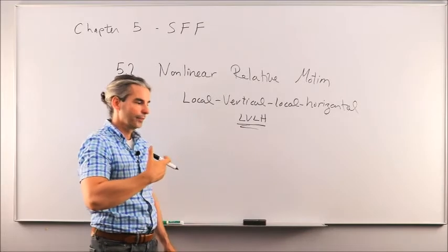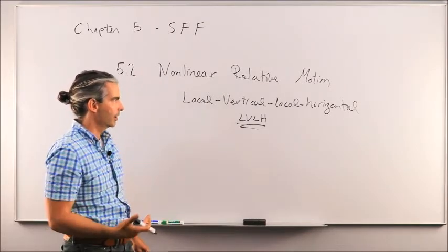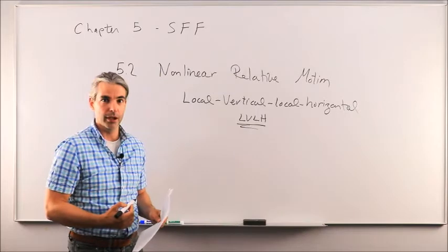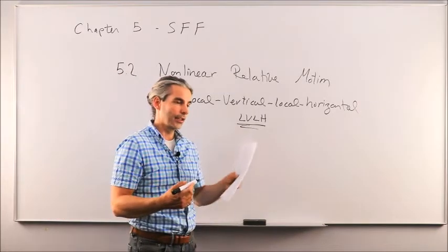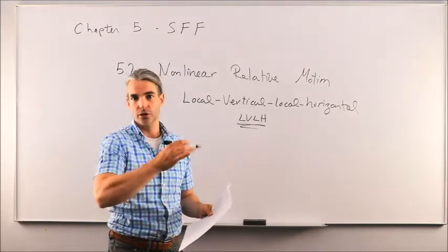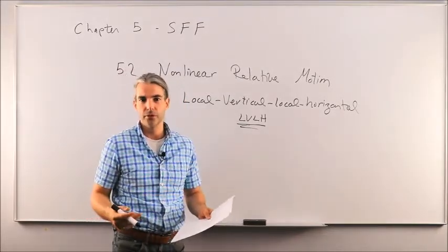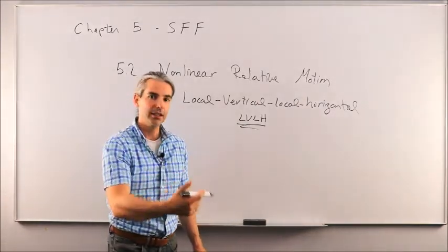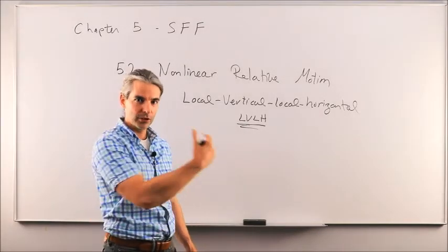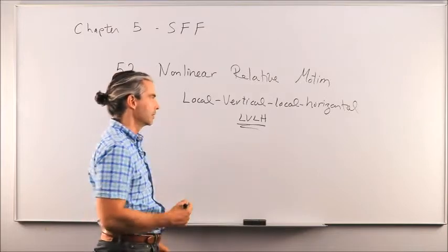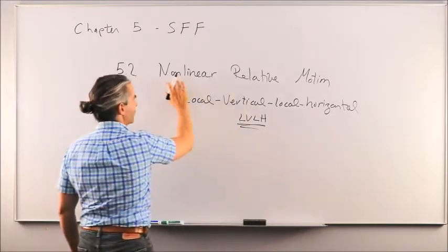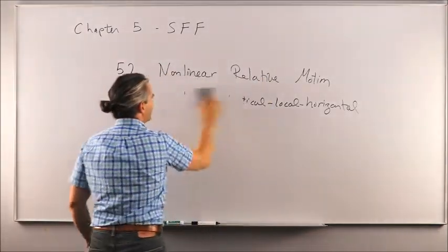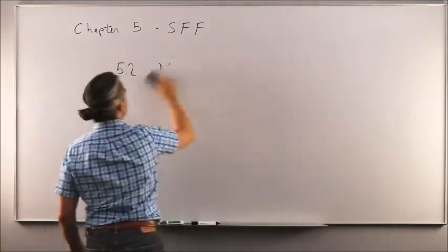Okay, so in the follow-up discussions in this chapter, we'll always refer to a target spacecraft and a chaser spacecraft. Okay, so we'll assume eventually that the target spacecraft is passively orbiting along its orbit, doing its thing, no propulsive maneuvers, and that the chaser spacecraft would use feedback control systems to actively maintain its relative position with respect to the target spacecraft to be whatever it needs to be, okay? But in order, again, to derive the nonlinear equations of relative motion, we'll need this new reference frame, LVLH, which is going to be organized as follows.